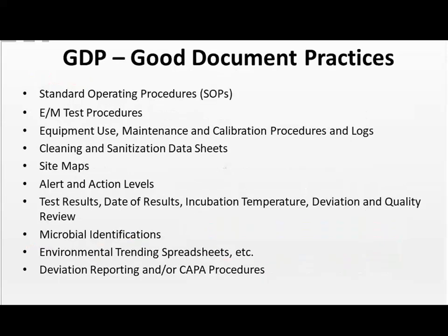Be sure, as part of your environmental monitoring program, that when you're training your analysts and your operators and you're taking samples, they have been trained on good documentation practices, that they understand standard operating procedures, they understand environmental monitoring test procedures, and how to document and sign and date testing samples and also test records.